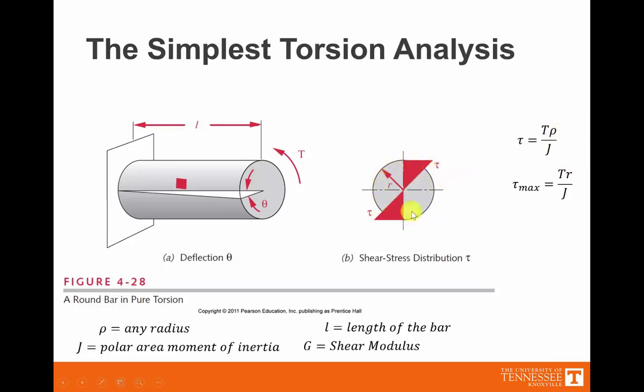And so that's why I said that it's the rim that has the highest stress. Notice I'm not putting tau xy because tau xy is occurring here, tau xz is occurring in this direction, and anywhere in between is some combination of the two. So I'm going to drop the xy convention because the shear stress is not necessarily in the xy or xz plane at any given spot.